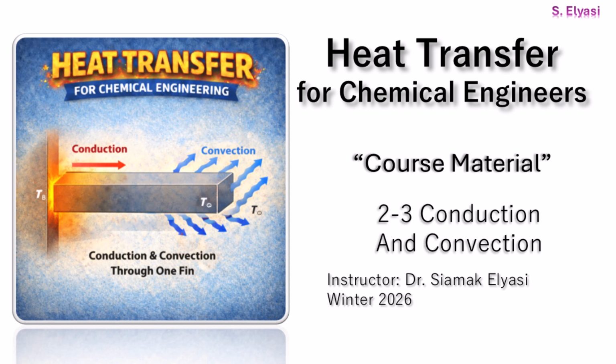Second, we get into convection systems, which is really all about using fins. The key here is an energy balance. You're basically saying that whatever heat is conducted into a tiny piece of the fin has to equal the heat that's lost to the air around it through convection. And from that simple idea, you get the core equation you need for designing any fin.